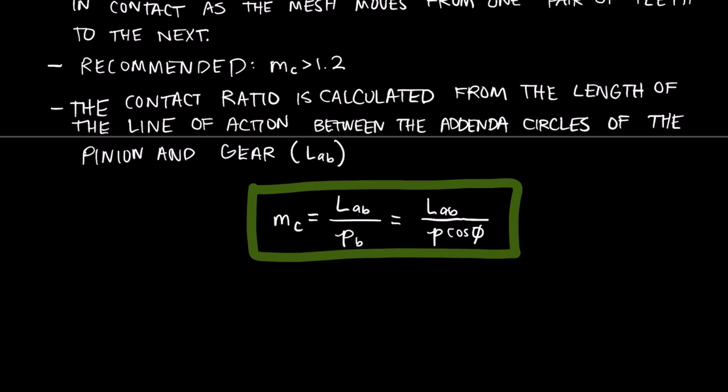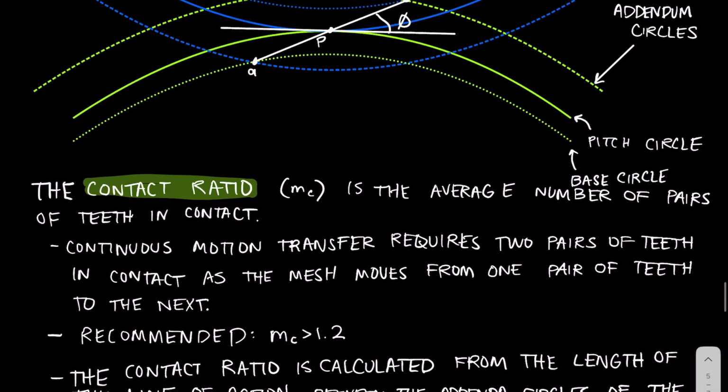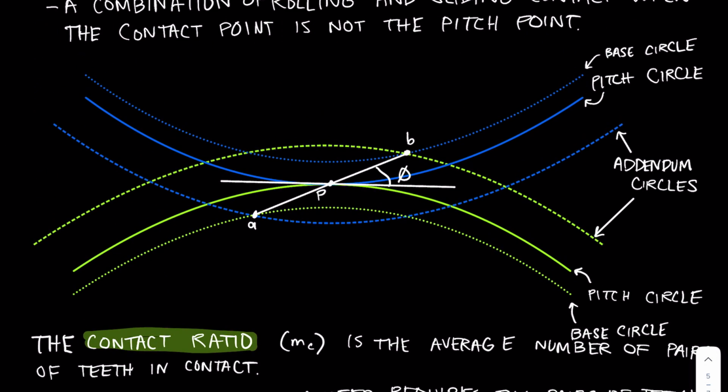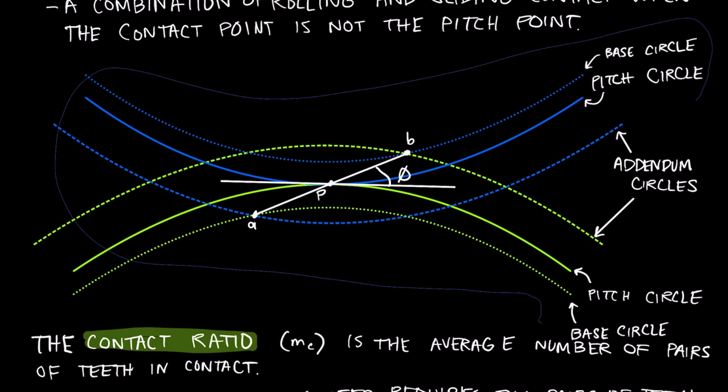So now let's talk about another concept, the concept of interference, which occurs when tooth profiles of meshing gears are not perfect involutes, which means they're not perfect conjugates of one another. And then when contact is occurring in that non-involute portion of the gear tooth, we have interference. So that's a lot of new terminology being thrown out all at once, but let's copy our image up here and I'll try to draw what I mean.